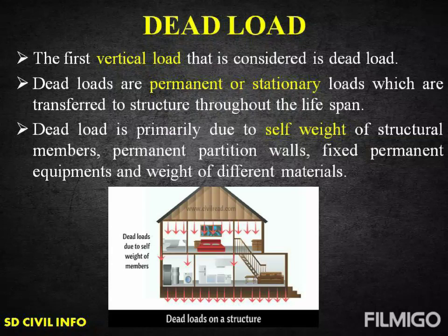What is dead load? The first vertical load that is considered to act on a structure is called dead load. Dead loads are permanent or stationary loads which are transferred to the structure throughout its lifespan. And dead load is primarily due to the self-weight of structural members, permanent partition walls, fixed permanent equipment, and weight of different materials that exist on the particular structure.